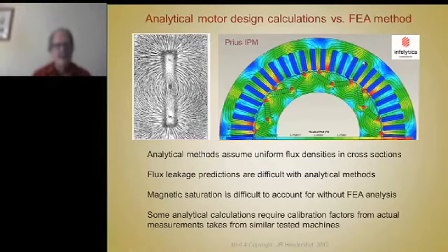The flux is highest in a cross-section where the magnetic reluctance is the lowest. In other words, the length of the path determines magnetic reluctance. A short path has lower reluctance than a long path, so the flux is going to tend to go around the shortest path. It doesn't want to go around the longest path because it takes more work, so to speak. To magnetize a short path takes less MMF than a long path. So there's going to be a voltage gradient across here. It's going to be higher there than it is there.